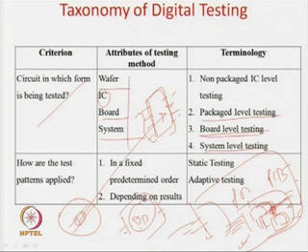So, the more system level you go, the fewer the number of pins you can access and the more difficult the testing is. So, this is a very raw testing which is called non-packaged IC level test. You can have lots of pins. So, the lower you go, or the more abstract level you go, the fewer pins you have, and so forth. But these are the different levels of testing in terms of when the circuit is tested.